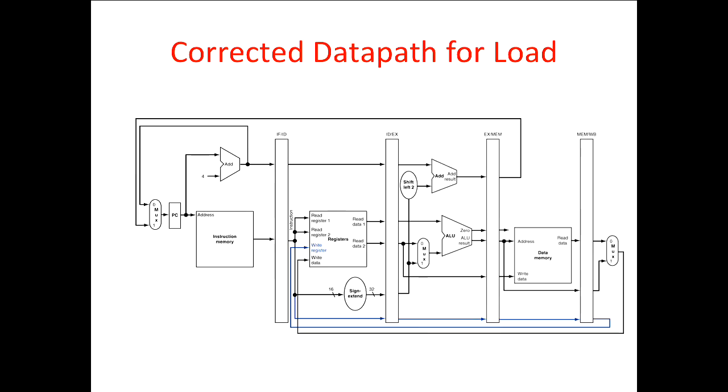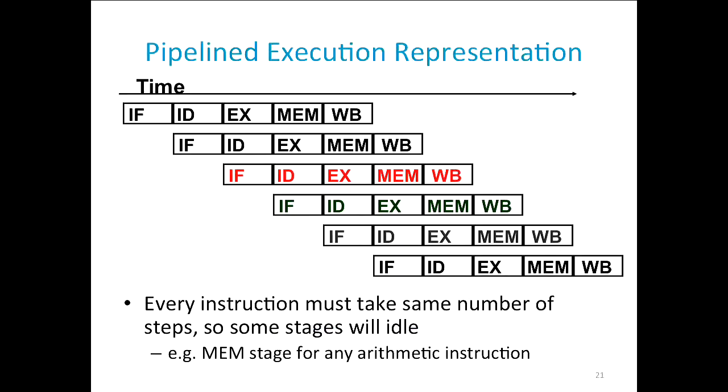Question? So if we were to write into the memory, is it possible to do the second stage and the last stage at the same time? If you were to write to the memory, right, the register, so the last part would use the register there. Yeah, we'll actually talk about that in a minute. So the question's about it seeming to be reading the registers and writing the registers at the same time in the same pipe stage. Yes, we'll talk about that in a second. Good call.